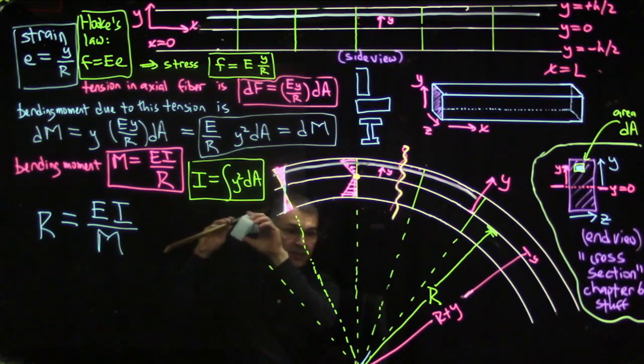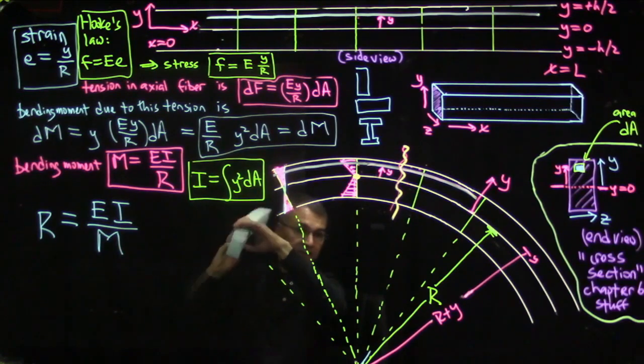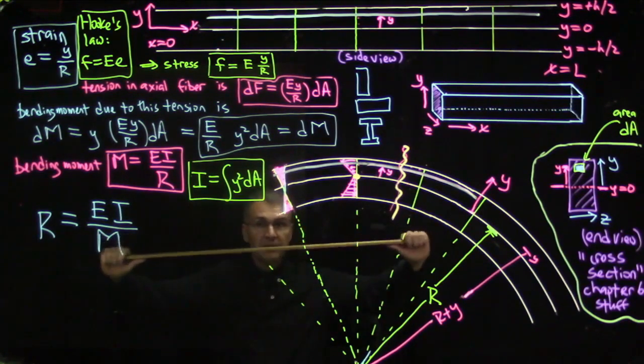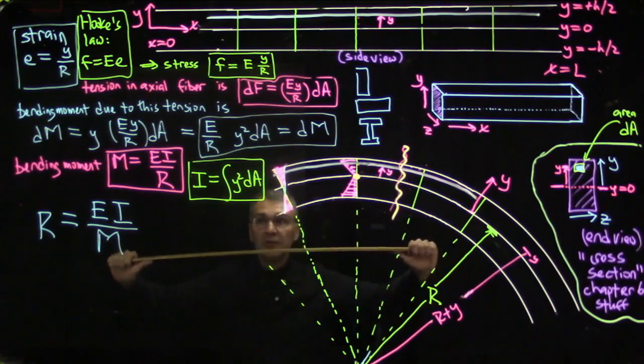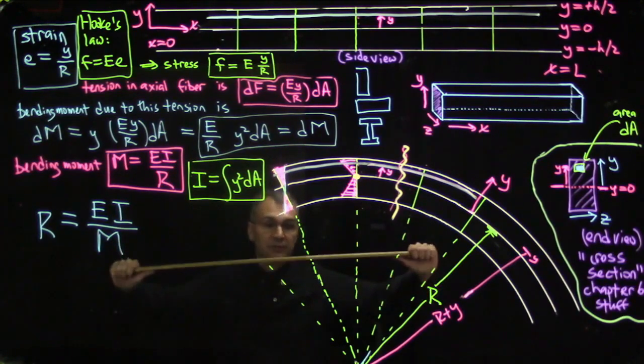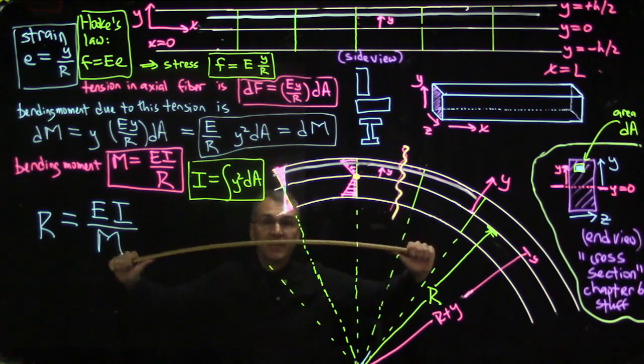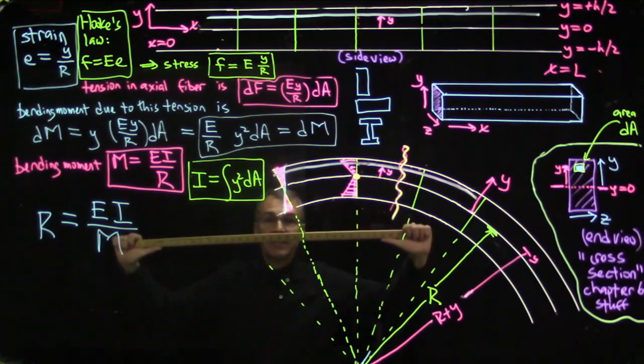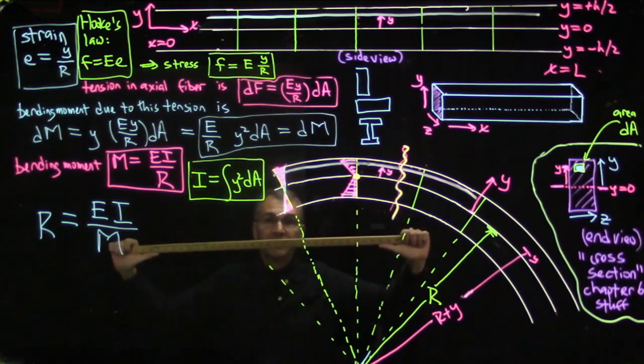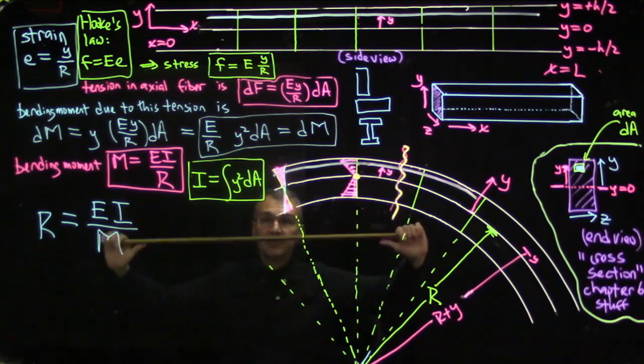That's like this way versus this way. Okay, so on end versus on the flat. If I try to bend this meter stick like this, there's a pretty small value of I, the second moment of area, when I put this ruler on the flat. The same ruler, I put it on end, and I've made the second moment of area about 10 times as big. And you can see that it is much more difficult.